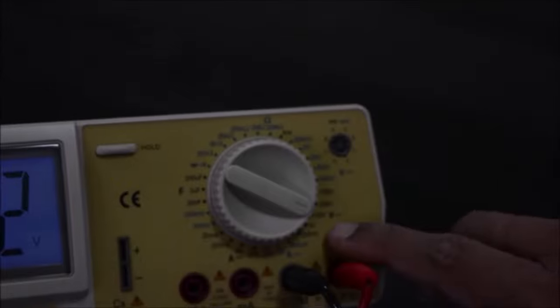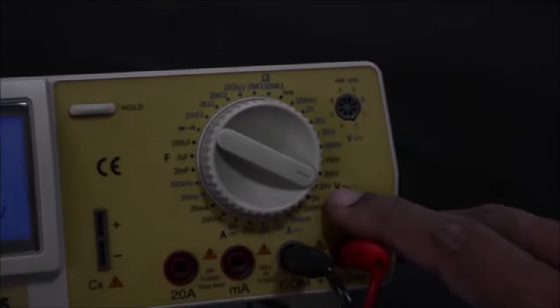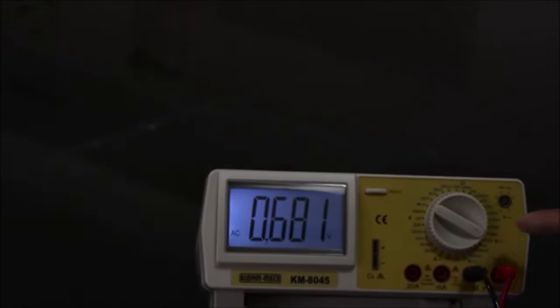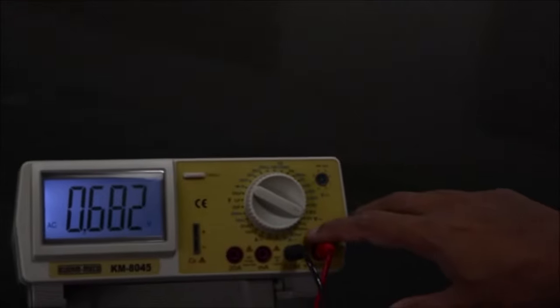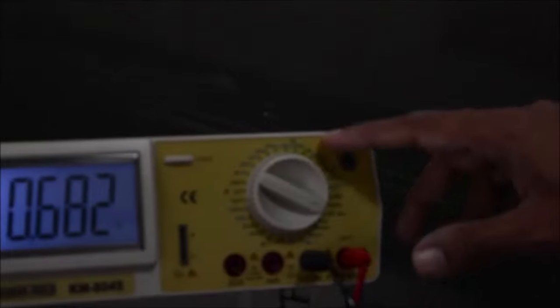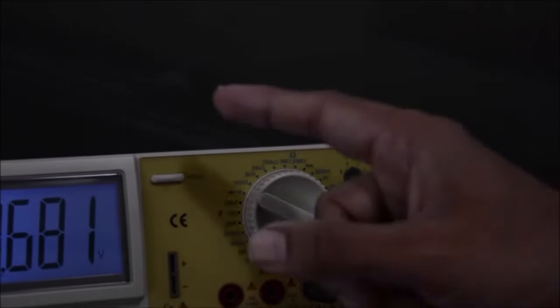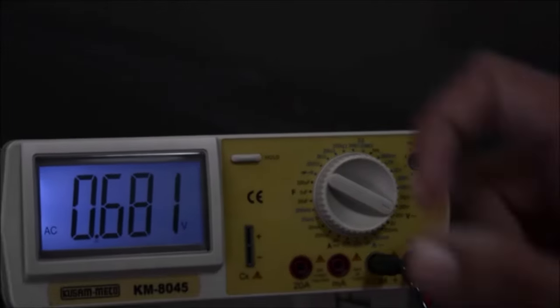And here if you notice I have set it at 20 volts, which means the maximum voltage which it can measure in this setting is 20 volts. Now, what can happen if you don't set it properly is that, suppose I set it at a lower value, let's say 2 volts or 200 millivolts. If I set it at a very low value, then in the case of series LCR, when I come near the resonance, it is going to overshoot and go beyond the full scale.